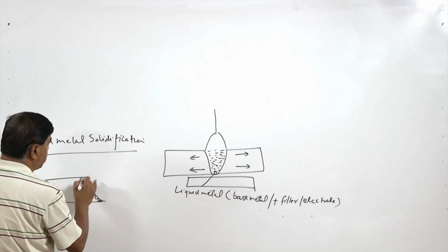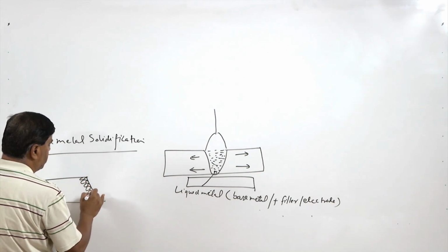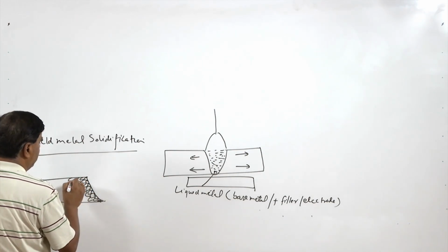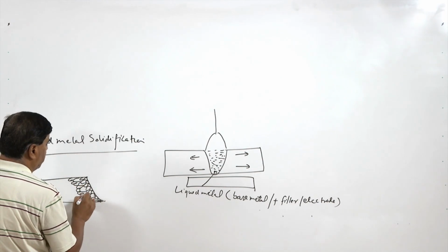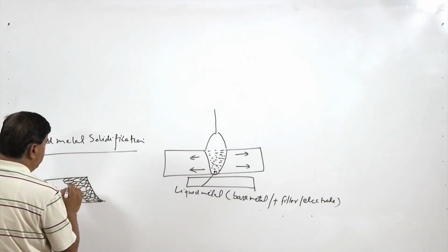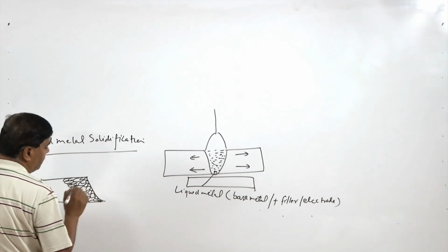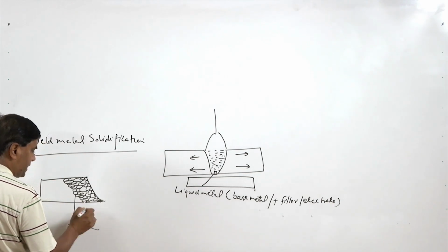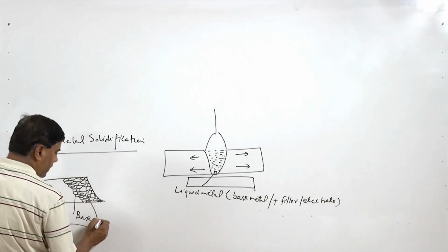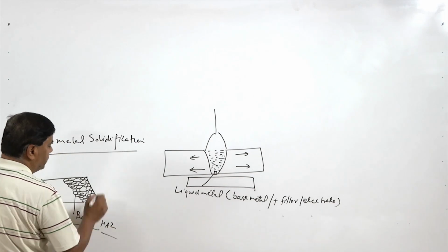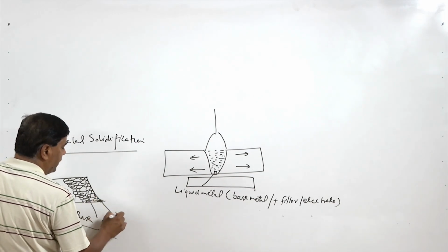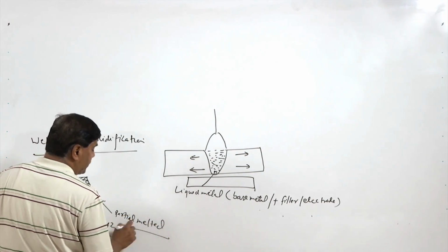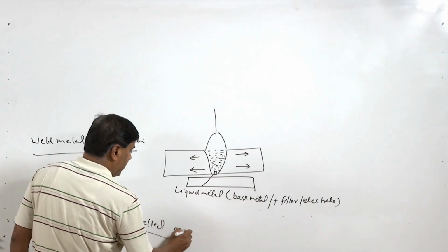like this. Next to that we will have heat affected zone which will have somewhat coarser structure like this, and then with the finer structure as we approach towards the base metal. So, far away from the fusion boundary there will be no effect of the heat, so that we can define as a base. Then next to that which is coarser, that will be defined as a heat affected zone, and then next to the fusion boundary there will be partially melted grains,